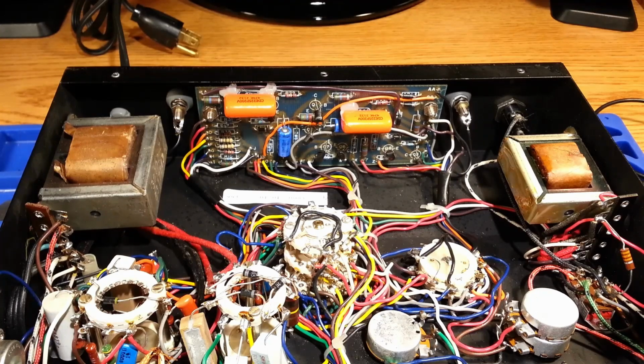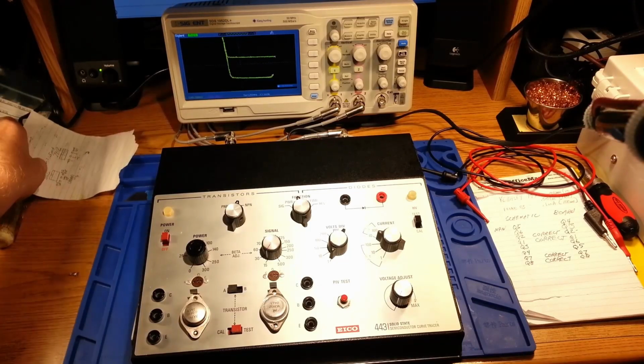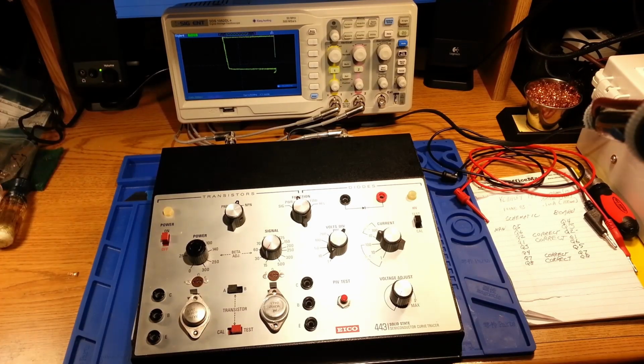So I'm going to put this thing back together and show hooking it up to the oscilloscope and show some testing. I am back, and it took a crap load of setting things up and adjusting on this guy. It's because they have a dedicated scope. Right now I don't yet, and also I've got a digital scope, and digital scopes do not work well with old school analog curve tracers, since the persistence on the trace and the sweep and everything, especially if you put it in XY mode, leaves something to be desired.